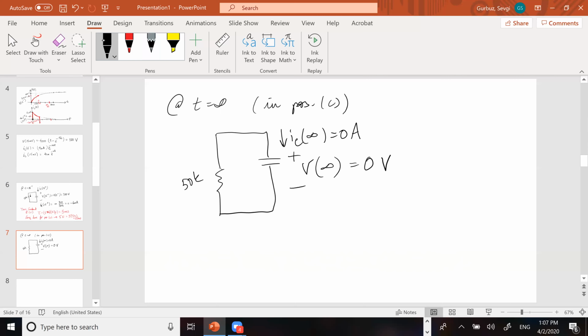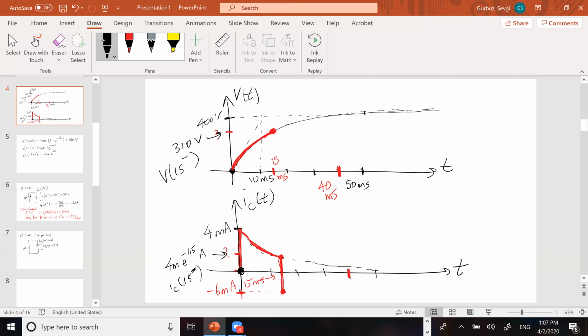So in the end, both of these two curves are going to trend down to 0, but they're going to trend down a bit faster than before. Note that there's a time constant of 5 milliseconds, so if I were to use the asymptote idea that I taught to you before about the slope, we would draw a steeper drop-off where it ended. Like here, it reached its final value at 40 milliseconds. And here we can apply the similar logic and draw it like this.